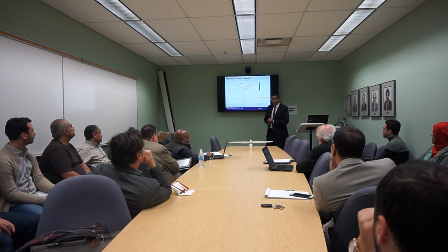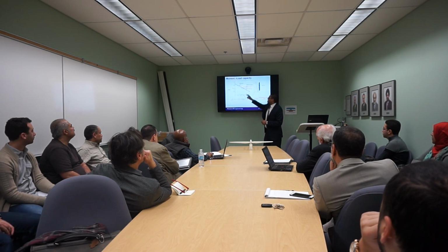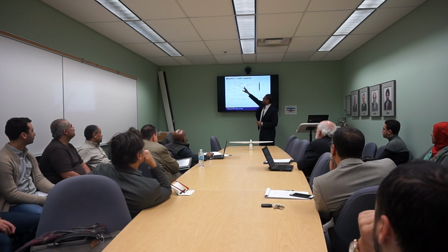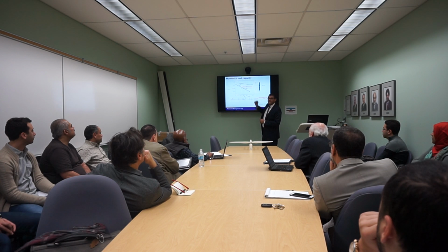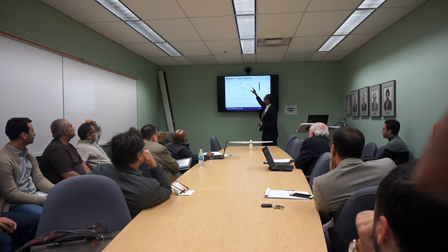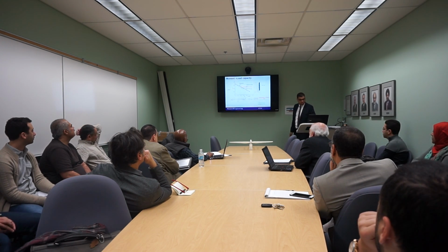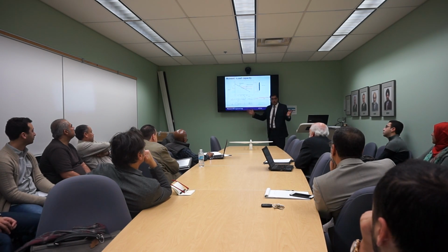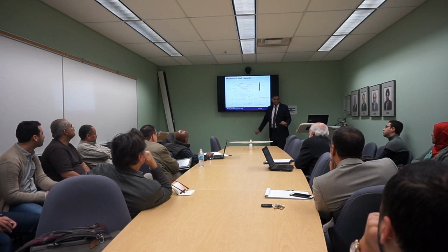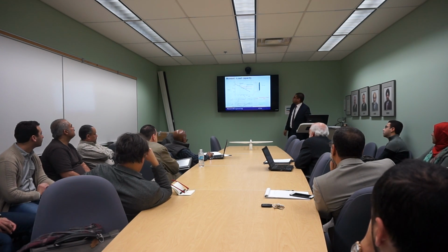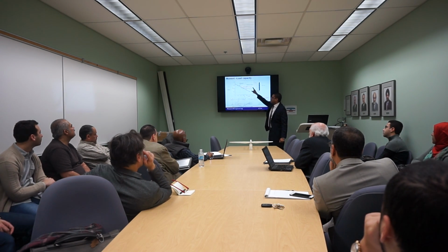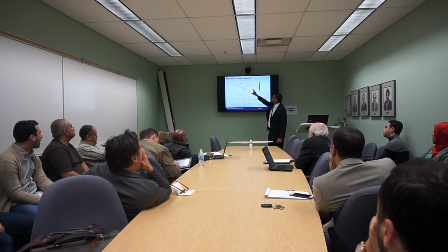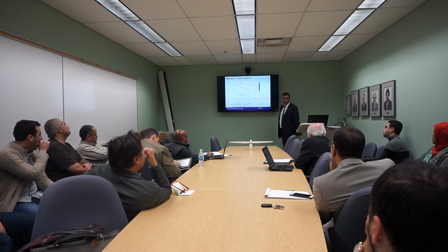But we don't have an equation for the hybrid foundation system. So we applied our maximum moment, maximum horizontal load for the hybrid system with different blade diameter. And from this line, we'll be able to get this new equation by adding the effect of the blade, depending on the blade diameter. So we can see here it's for different blade diameter, starting from diameter 16 ending with diameter 22.